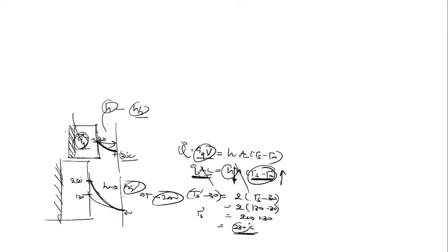What about the gradient at the wall? As you know, if you use the boundary condition at the surface, then minus k into dT upon dx should be equal to h into (Ts minus T infinity), or this should be equal to what? Qg into volume. Or you can say also h into A, since you are writing volume, that's why area should multiply here.